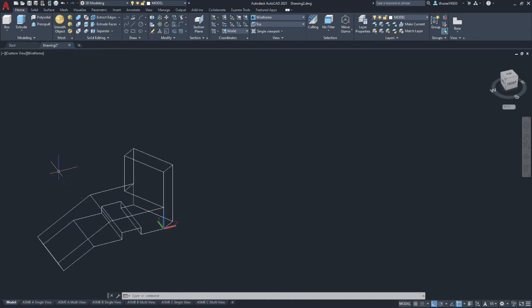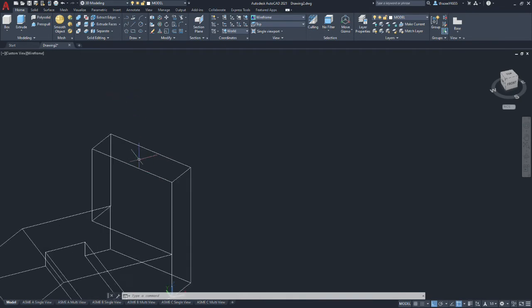And then we'll get into changing our last two simple features, and then we'll get into changing the UCS. So the last two simple features are the slot in the flange, and there's a hole going through the top of this component here. So we want to continue to work in the top mode. Our slot that's in the top, we'll draw a line from end to end. We'll accept that line, and then we're going to do an offset of 1 inch. I accidentally went too far. Yeah, that's our 1 inch offset.